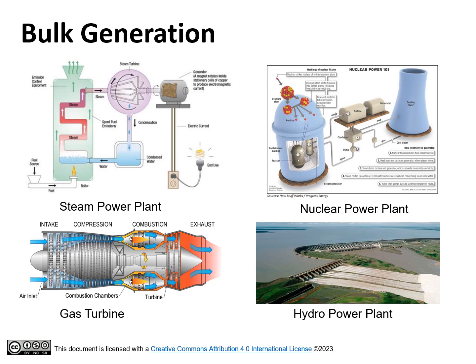To convert mechanical energy into electrical energy, power plants usually use a synchronous generator connected to the turbine shaft. Synchronous generators are used in power plants to generate AC power at a fixed frequency equal to 60 Hertz in the US and 50 Hertz in Europe.